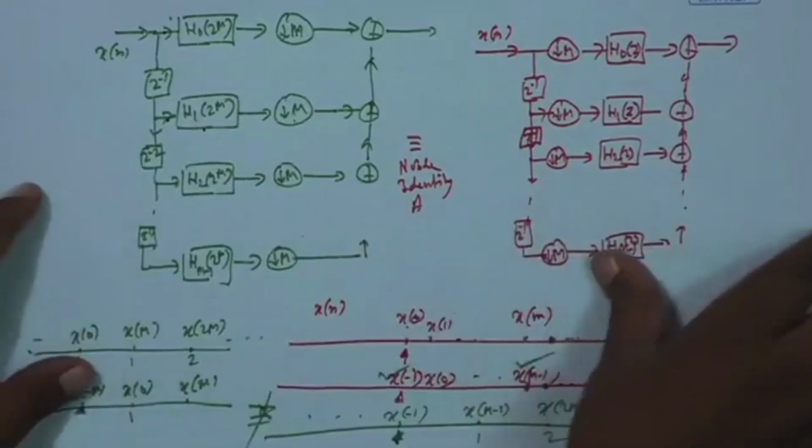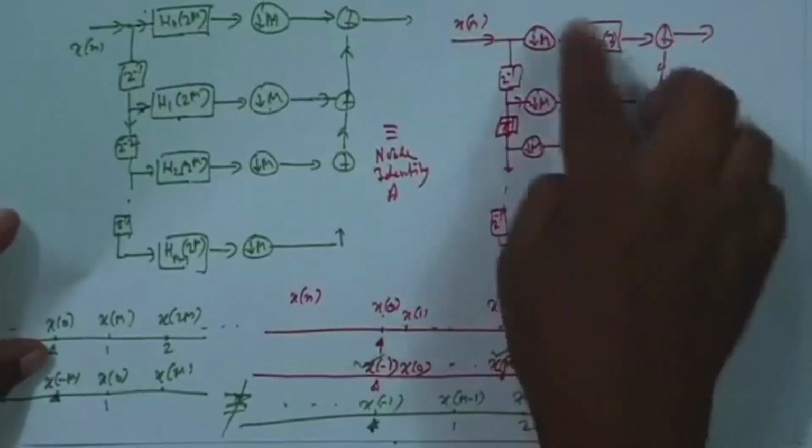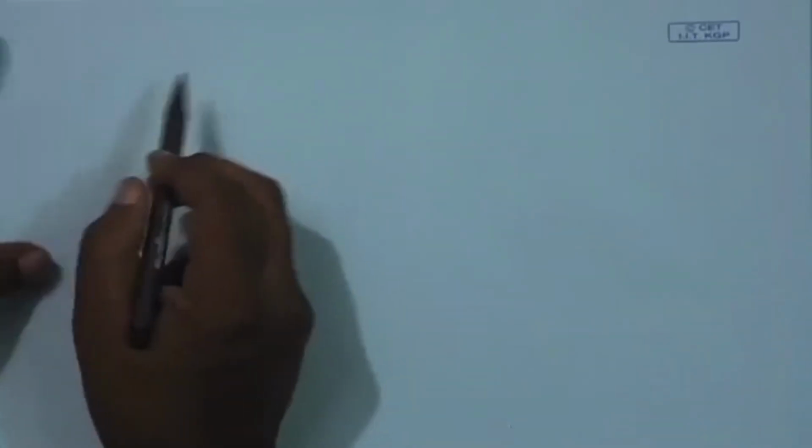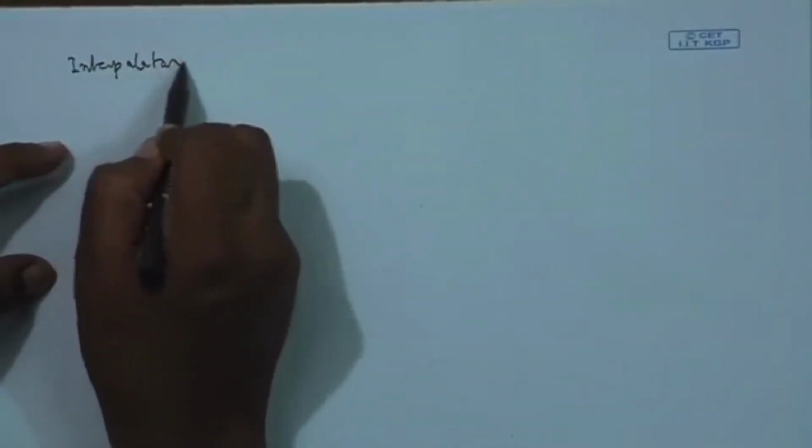But anyway, this is an efficient decimator structure we have seen, filters are working at a lower rate. Now we go for the other version, that is the expander. What do we do in the case of interpolation, efficient interpolation? What do we do in an interpolator?